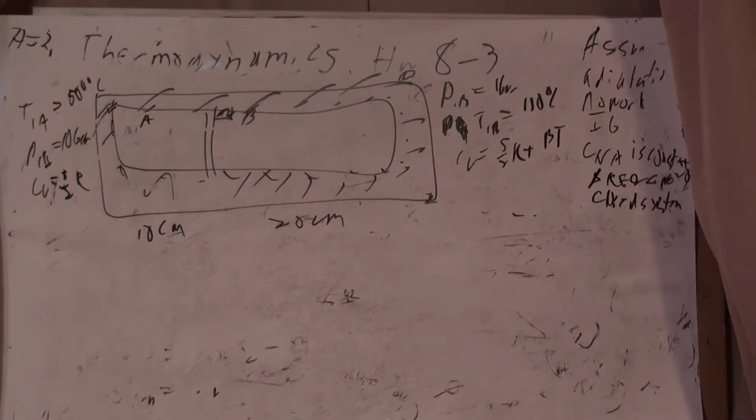So the first thing we should at least do is the full analysis. We will need to figure out the final temperature and final pressure, but let's do our full analysis first. Obviously, there's going to be missing information in terms of temperatures, pressures, and all that good stuff. But let's do our full analysis first to get a sense of what our mass, energy, and entropy balance tell us. So let's move forward with that in mind.